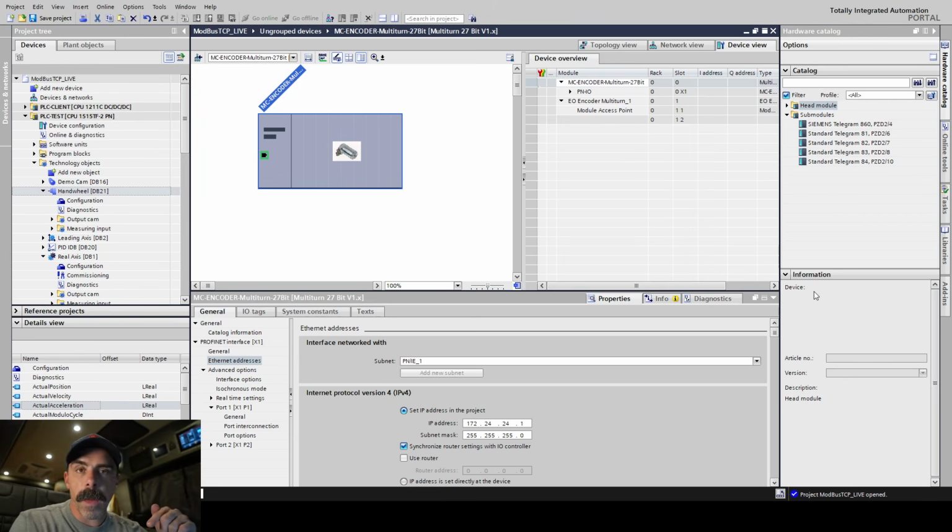And the user that was asking me about what you need in order to bring in Profinet information: you do need a telegram. There's telegram 81, 82, 83, 84, and then apparently a Siemens telegram 860. So anytime you see a number over 100, that is a Siemens specific telegram. Anything under 100 is going to be an industry standard telegram by those definitions. So it looks like what we have here is 4 different types of industry standard telegrams: 81, 82, 83, 84.